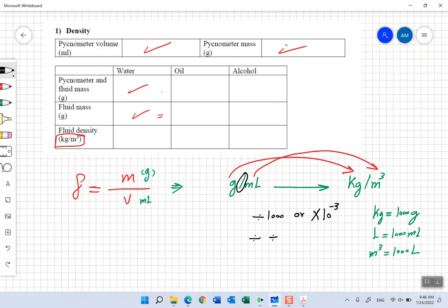So instead of adding 2 division marks, I can only multiply by the rate between milliliter and meter cubed, which is 1000 by 1000. Why? Because meter cubed is 1000 liter and the liter is 1000 milliliter. So I will multiply by 1000 and another 1000.